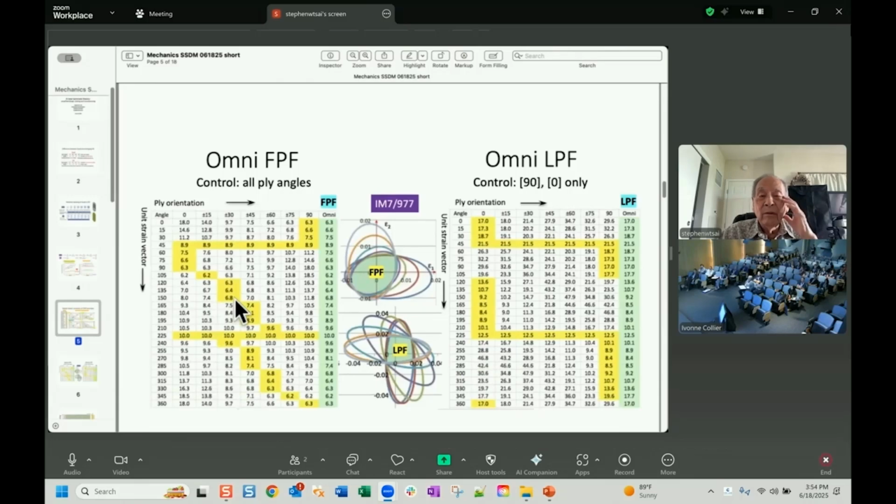And in the case of failure envelope, it's the same thing. To the left is the first ply failure. We plot all the failure envelopes in strain space. This is all for the degraded, so the last ply failures. It turns out that the first ply failure is controlled by all angles depending on the combination of the strain, whereas the last ply failure is only the longitudinal tension and compression. So the last ply failure is much easier because you only have two parameters to deal with.